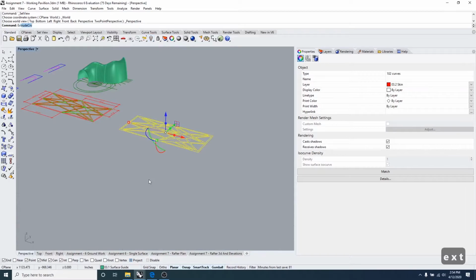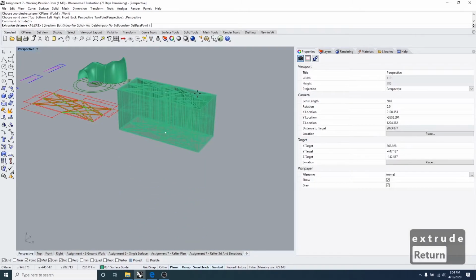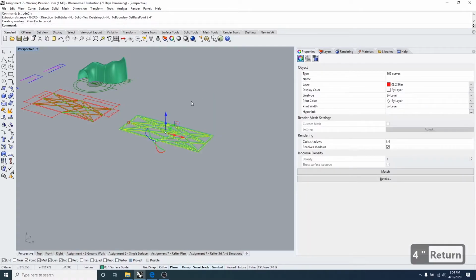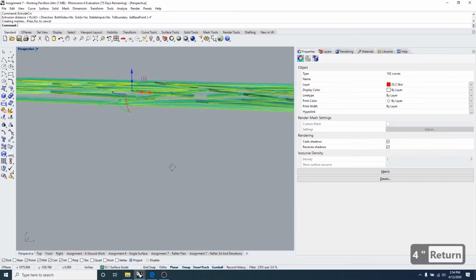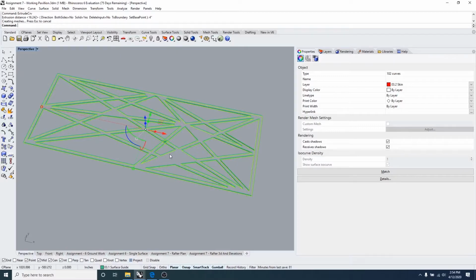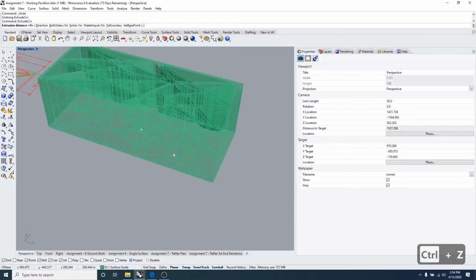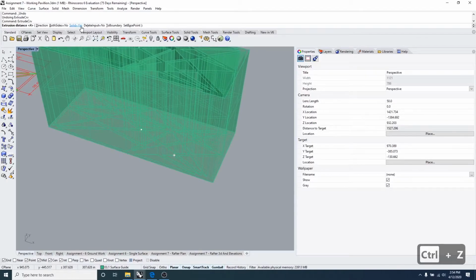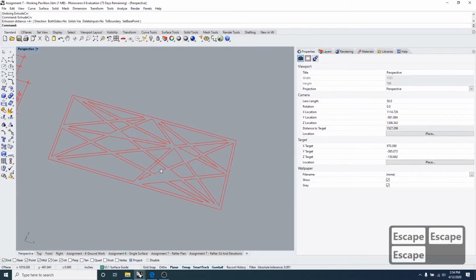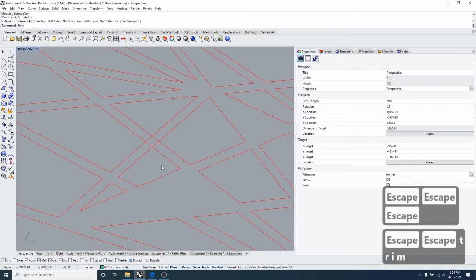And I'm going to extrude this. And I'm going to give it a thickness. I'm going to say this is going to be 4-inch thick. Okay. So we're running into some issues. It's not a complete solid. I didn't check my options. We do have a solid yes, so that means we have an intersection of a few lines, and you can see it right there. That's why this is failing. So let me just trim those.